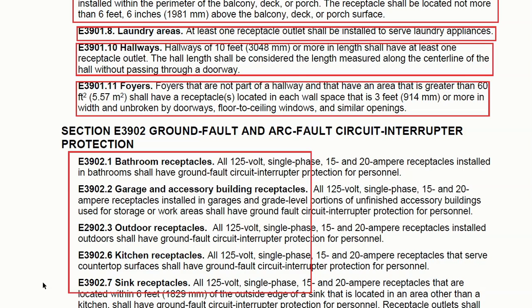The reason is, ground fault interrupt protects you from getting electrocuted when there's water involved. So basically what it's doing is it has the two sides of the plug. You have the neutral side and the hot side, and then you have a ground. And what it's looking for is if it has 120 volts going on one side of the plug, 120 volts needs to come back in. If it's going anywhere else, it's going to trip and protect whatever is taking that electricity. So they're designed to protect you. Your breakers are designed to protect your house from catching on fire, not to protect you, okay?